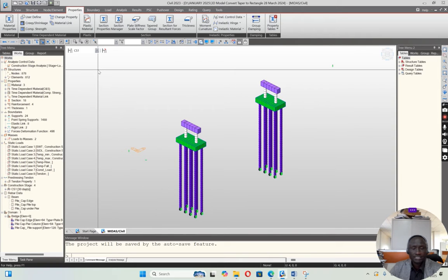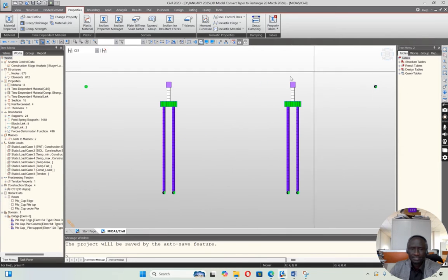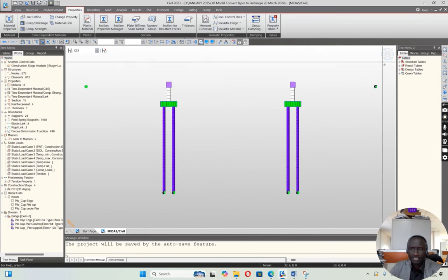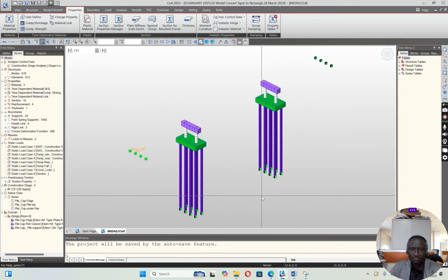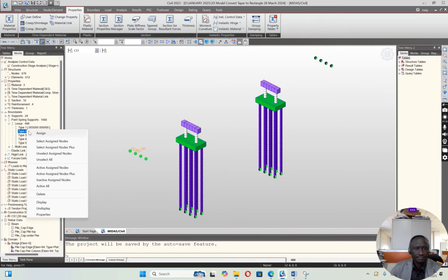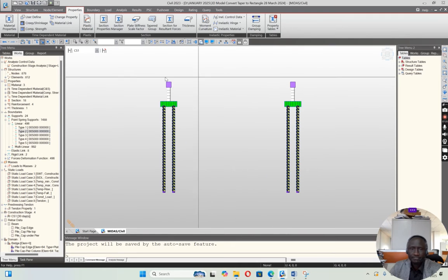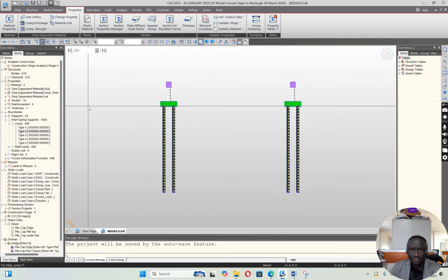So basically that is what you need. Because of the geotechnical findings, this is going to be both friction and end bearing. The end bearing is simulated in the boundary condition, and then along the piles you have what they call the soil structure interaction, the spring constant, to simulate the different layers of soils.